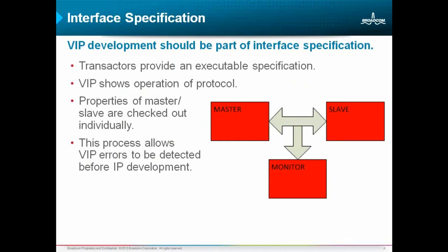And what we can do, as well as running this sort of test bench, is you can set up some proofs where you bind the monitor to either the master or the slave and try proving your monitor assertions about the individual components of your verification IP.